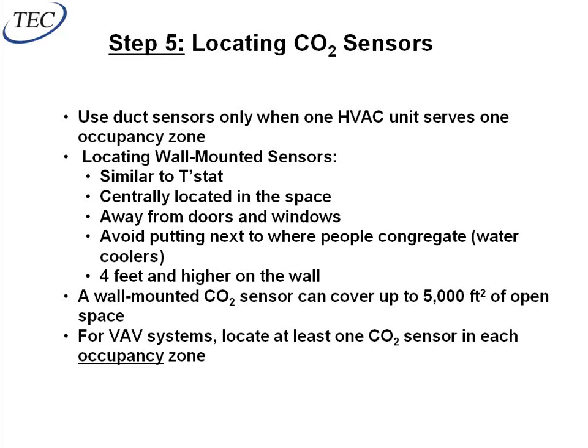Return ducts make sense only in large open areas like a gymnasium where all the air is kind of being pulled together anyway. So a gymnasium or a movie theater or something like that where it's one piece of equipment for one large room, that makes sense. Putting it in an area that has zone dampers or even has constant volume but has cubicle walls, partition walls between the private offices and the cubicles, for those you've got to put it in the space.